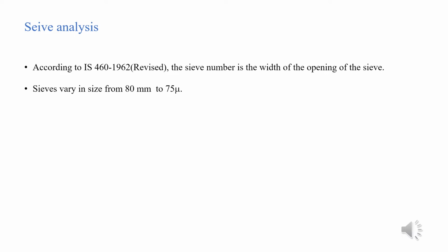So we have talked about sieve analysis, right? Usually the coarse grained soils are subjected to sieve analysis. So what are sieves? Basically sieves are like pans which have wire screens with different square openings.